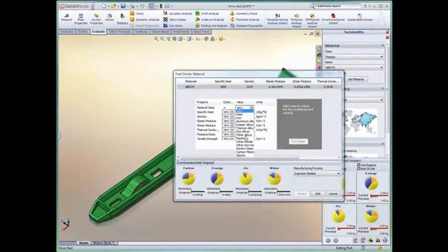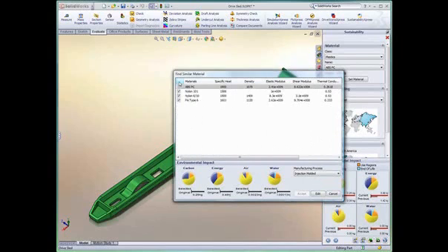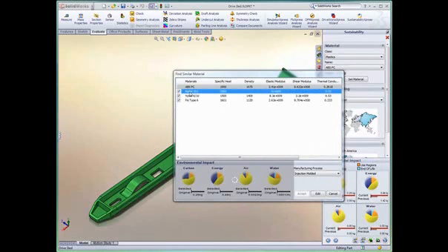That's why SustainabilityXpress has the ability to find similar materials. Let's say we search for materials with higher tensile strength. When I have a suspect material, I simply click on it, and you can see the graphs at the bottom with the new result compared with the baseline.